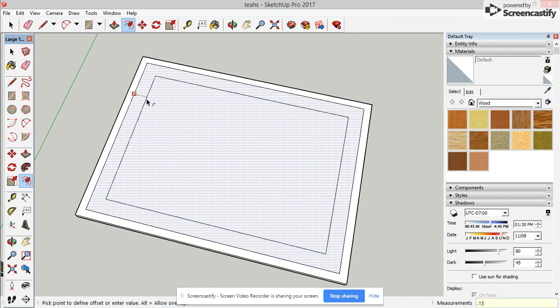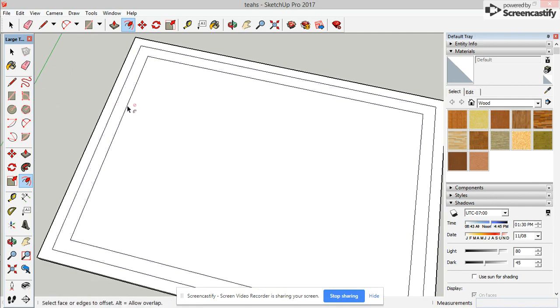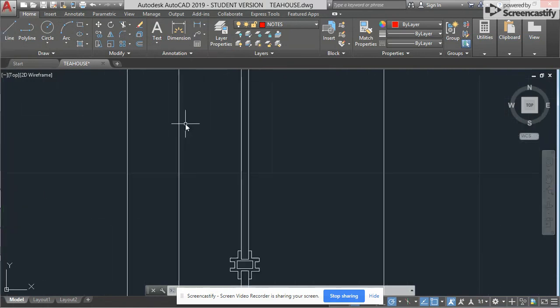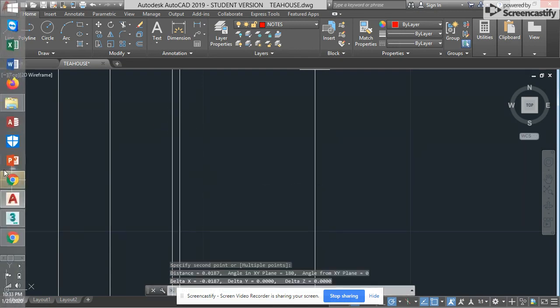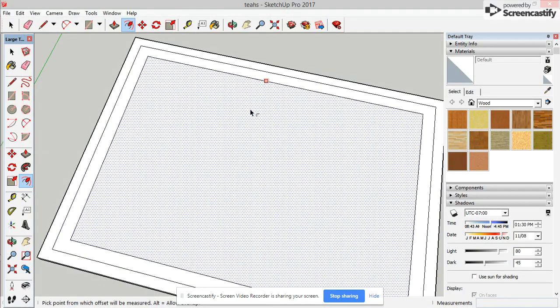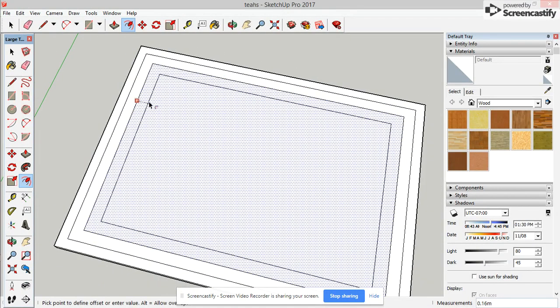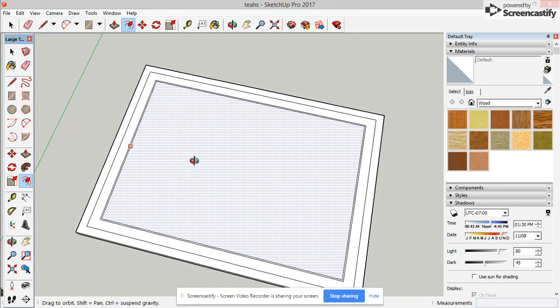We're going to offset again 0.15. That's going to be the edge of the glass. So we have this edge. This is the edge of the glass. And then the thickness of the glass, right here, that thickness, I don't remember, it is 0.0187. Very interesting. 0.0187. So we're going to offset that 0.0187. So there's our thickness of the glass that we offset all the way around.